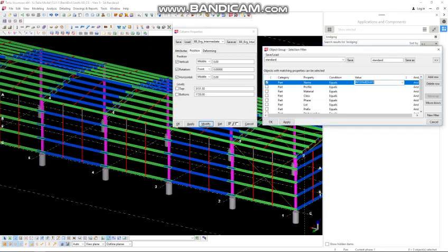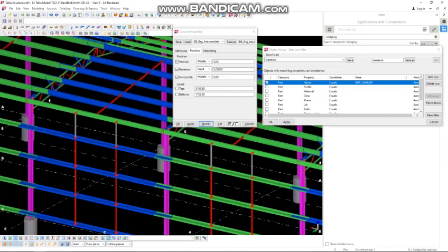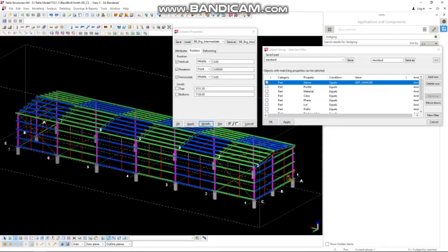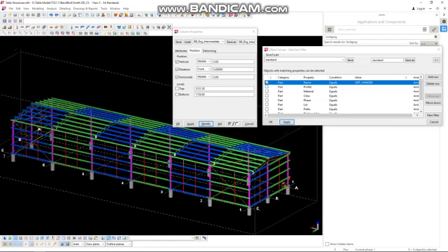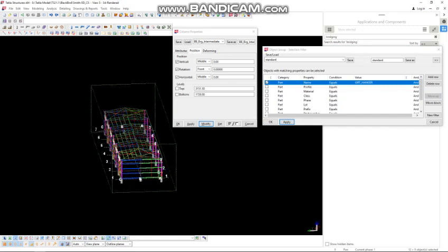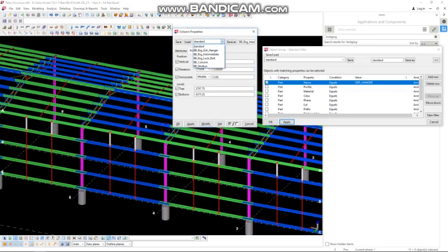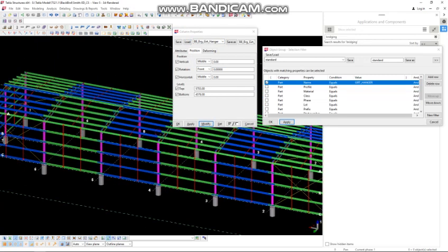And the last would be the girt hanger. Just click this one. It should be useful if we have already created all of those areas with girts and purlin, so we can do it once only. So this is just my presentation. Then we have to select the girt hanger, for example here. So I think it's only the girt hanger. So here, just double click again the girt hanger, and then just load this BR bridging girt hanger, and then we have to modify. Okay, so we have already here the correct items for our bridging.